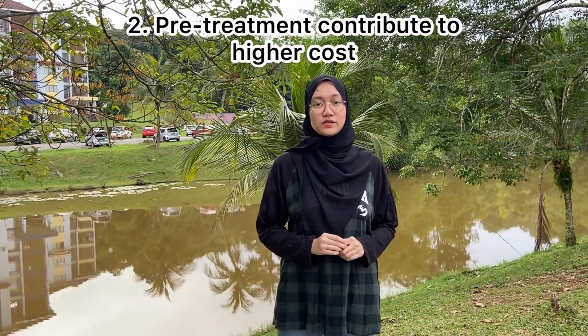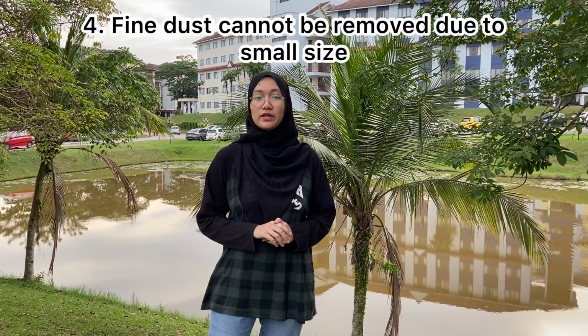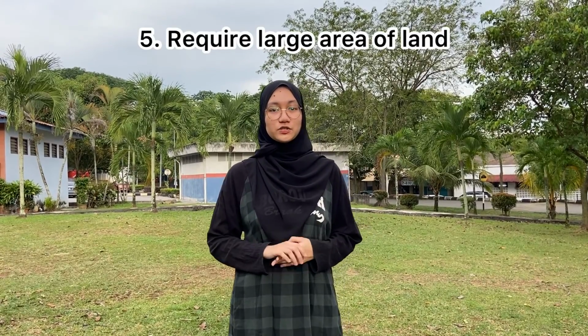However, this pre-treatment contributes to a higher initial cost. Next, a virus cannot be trapped by sand filtration due to its small size. Furthermore, fine dust also cannot be removed because it is too small. Apart from that, sand filtration requires a large area of land to build the plant. Since the world's population has increased throughout the years, this has become one of the biggest challenges faced by sand filtration.